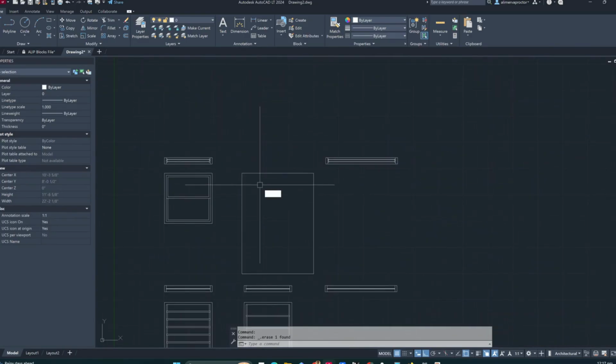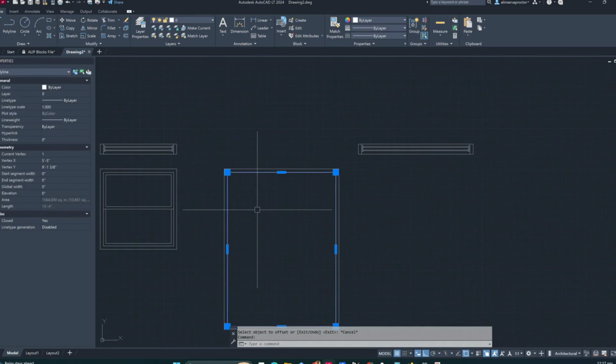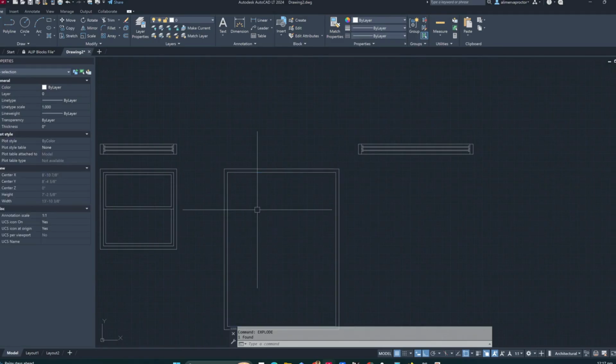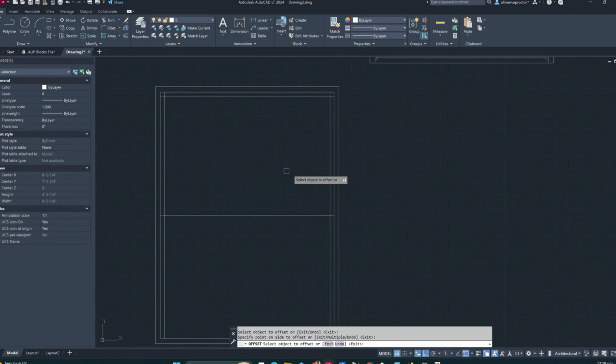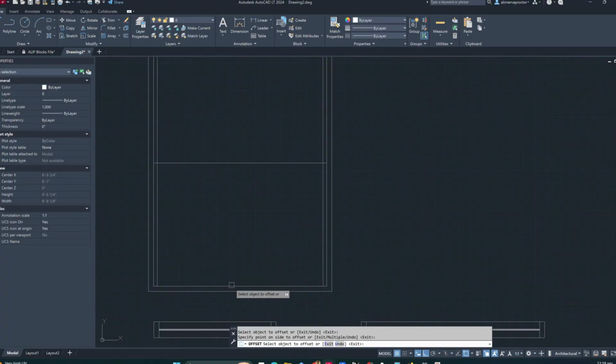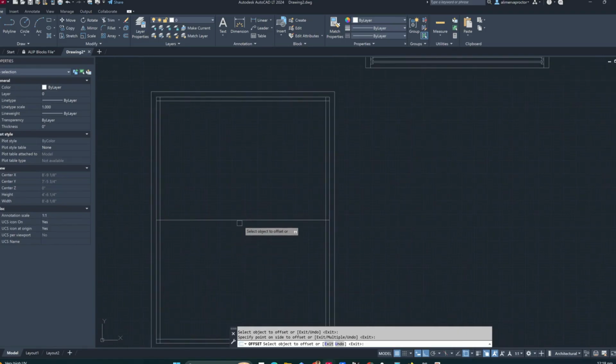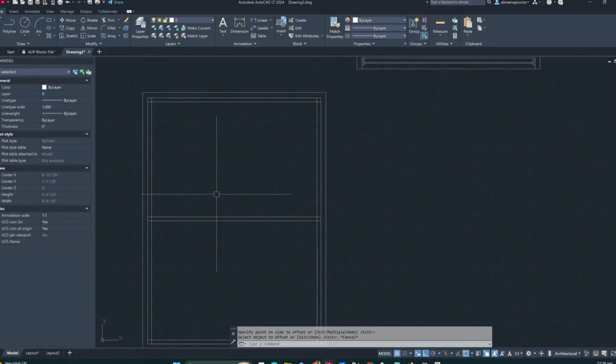So boom, I'm going to offset in my 1 inch. I'm going to already explode this one, right? Explode. We're going to do a line from this point to this point, right? Remember, everything is already exploded. So we're going to offset, right? We offset in 0.75 in. I'm going to show you some different commands when we're doing that. This one, okay? So we go into the two sides, we're going up, and we're also going up, right? So that is what we have.